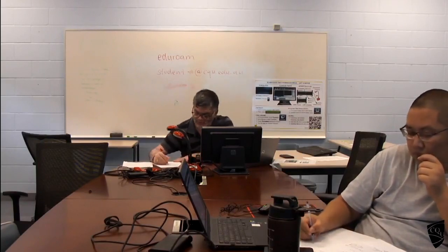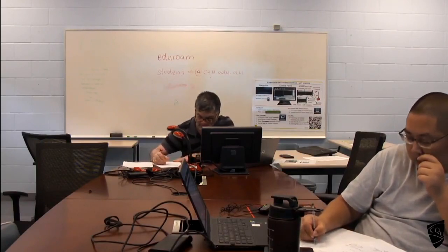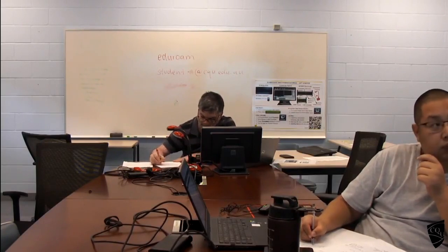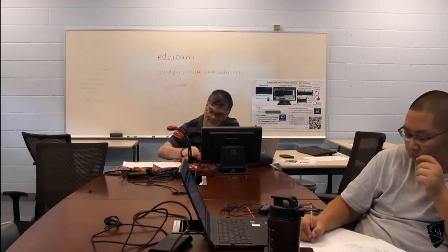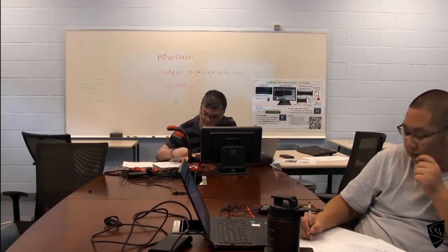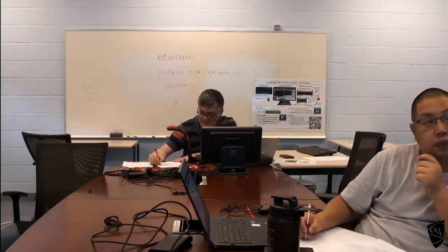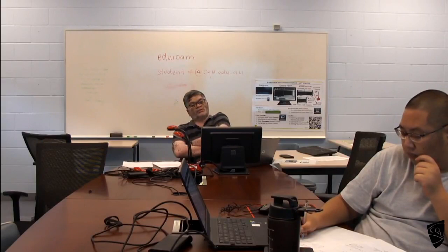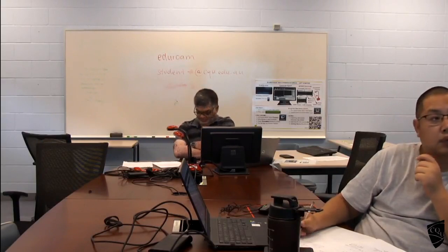Then if you want the I value about another axis which is parallel to that, it is equal to the centroidal axis I plus A d square. d is the distance between these. So the I about any axis can be given as Ig plus A d square.